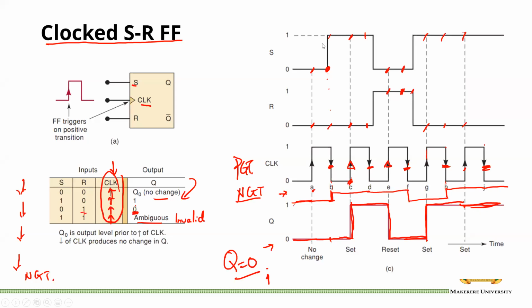Let me see some questions. Vivian is very lost and wants a recap. More clarification, Ivan, on whether the clock is a control signal. The clock is not a control signal. The control signals are the inputs. The clock is just a synchronous signal. It implements the synchronism within the system.